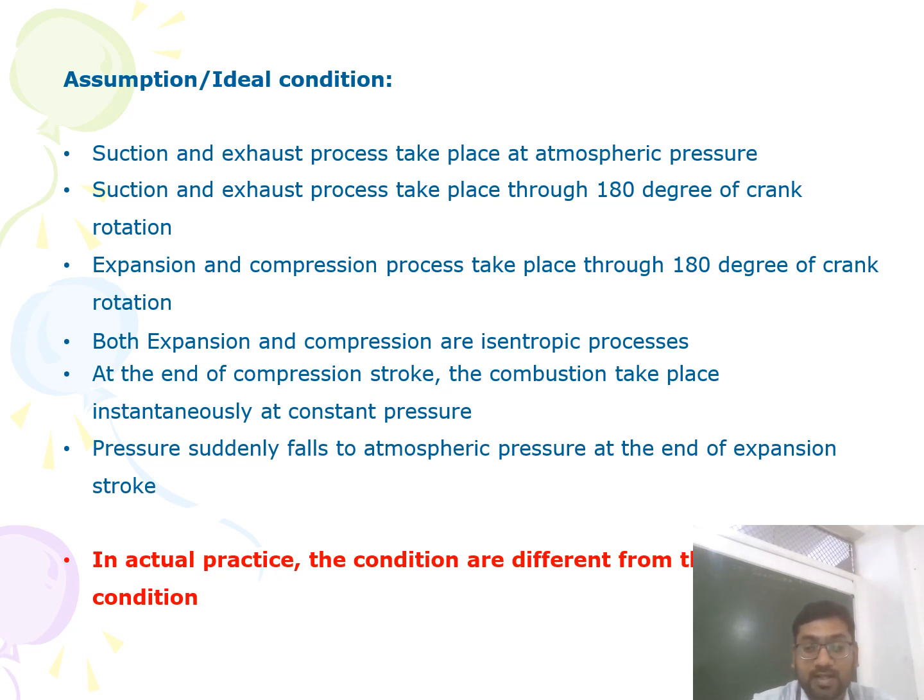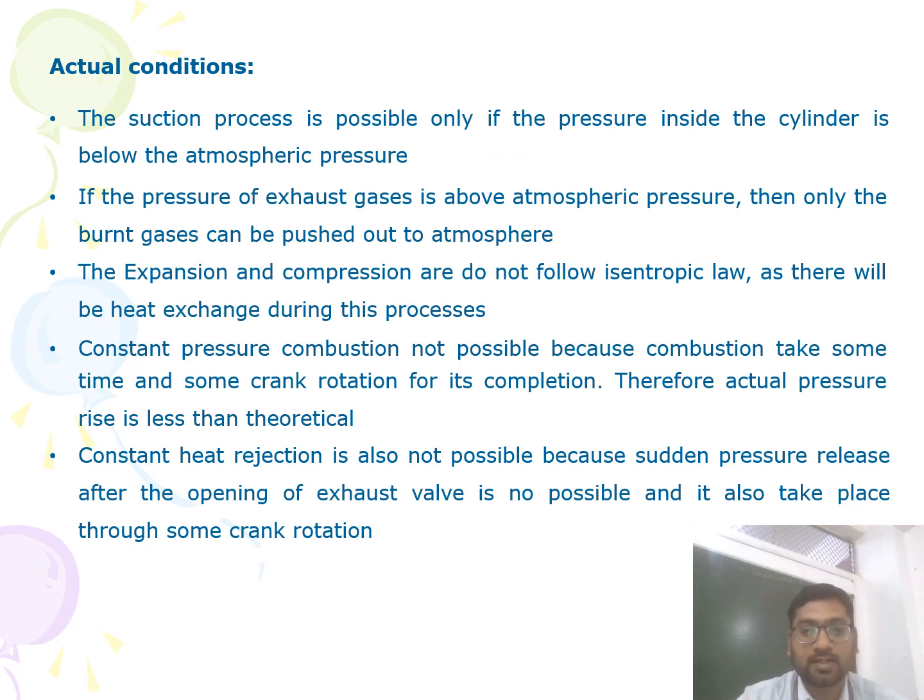But when you study the actual condition, it is totally different from the theoretical assumptions. As I said earlier, students, the actual scenario is totally different from the ideal one. First, in the actual condition, the suction process is possible only if the pressure inside the cylinder is below atmospheric pressure. As I also mentioned in the previous lecture, at the same pressure between two systems, fluid flow never occurs. So for fluid flow, there has to be a pressure difference.